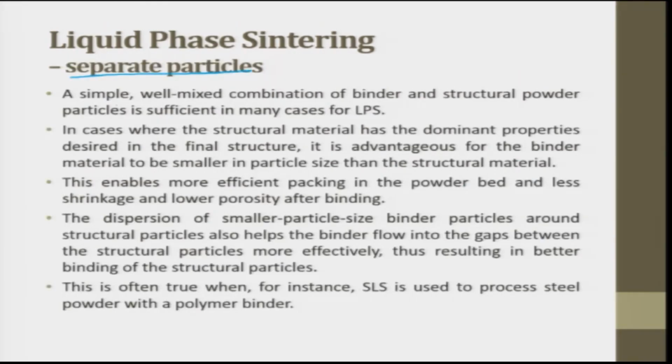Separate particles: a simple well mixed combination of binder and structural powder particles is sufficient in many cases of LPS. In case where the structural material has the dominant property desired in the final structure, it is advantageous for the binder material to be smaller in particle size than the structural material. That means to say, only tungsten carbide you would like to have, but cobalt is needed as a binder. So here the toughness property is sacrificed and you use it only for compressive load and high temperature withstanding